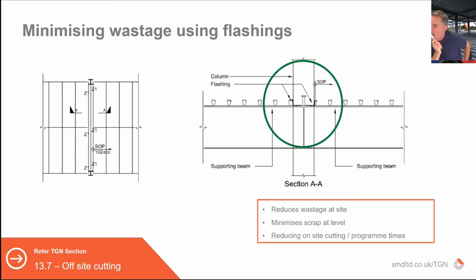Yeah, and you can have problems with this penetrating nail, where, if it's pre-installed fire protection and the fire protection has gone brittle, then that nail can actually cause damage to the intumescent. I would suggest that probably comes more on non-composite beams because you're using a heavier nail and you potentially got a thinner flange because you can get away with it because you haven't got welded studs. That's why I asked the question about the crushed ends. Right. Yeah. Okay. No, thanks for that, Bob.